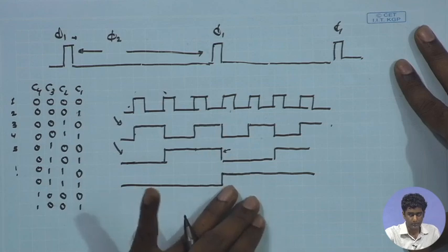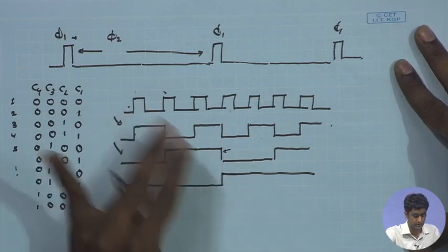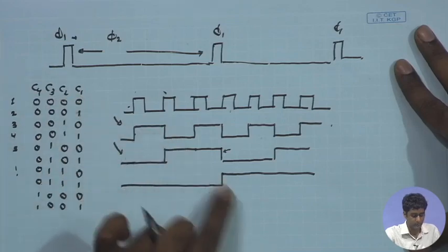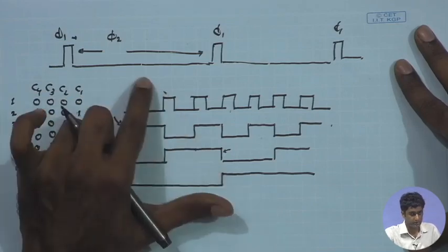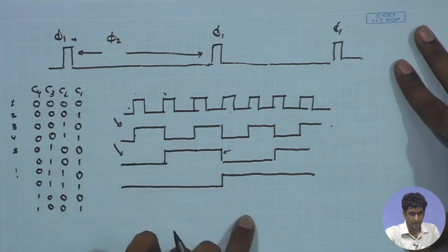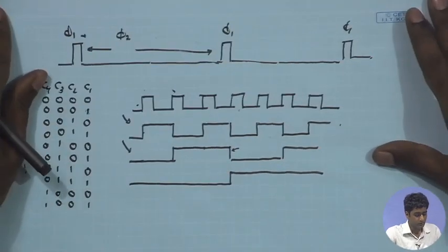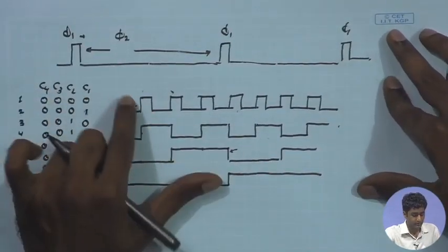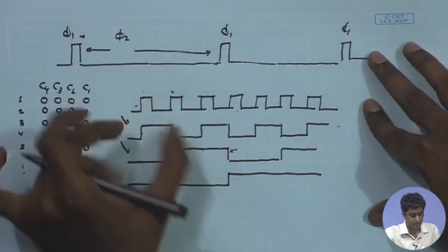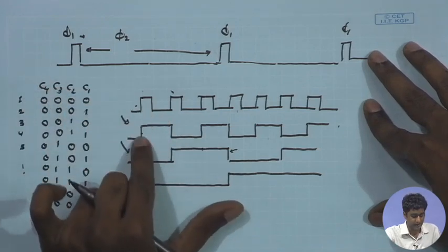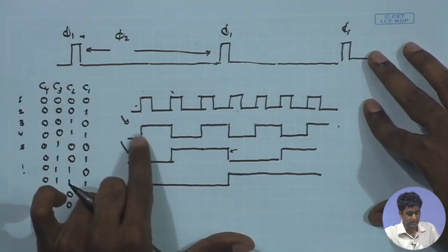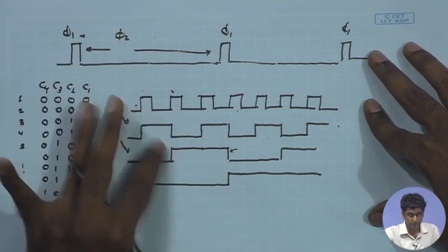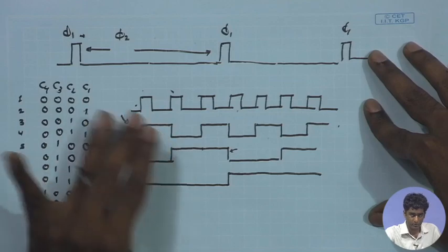So, this is the operation we would like to implement using digital circuitry. The counters, or the circuitry implementing the counters, ultimately should be able to implement this divide by 2 operation, starting from the original clock and going on dividing the clock by 2. The other important consideration is that the overall operation of each of these bits is going to be edge triggered. So, the transition happens at the edges of the previous clock or the previous phase. So, we need to look at the edge triggered operation, and therefore, we are going to look at the flip flop.